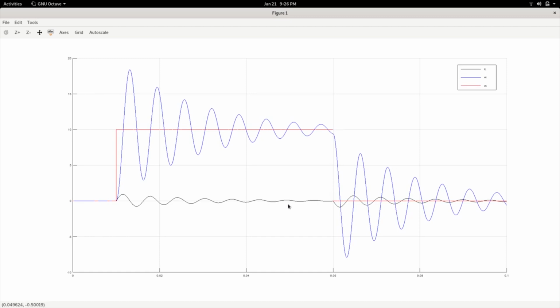Now let us say that we keep the final time, end time, at 0.05 or 50 milliseconds. So you should see that the simulation should end here. And if I put resume is equal to 1 and continue, the simulation should seamlessly continue from here onwards the second time round. So let us see if that happens.